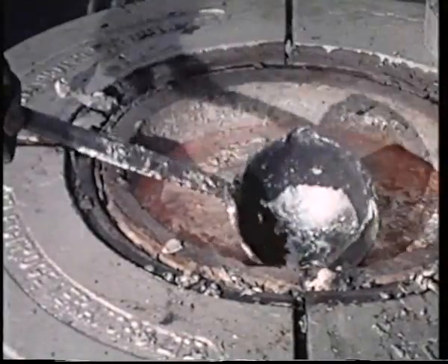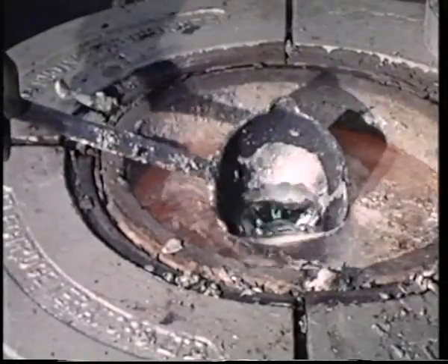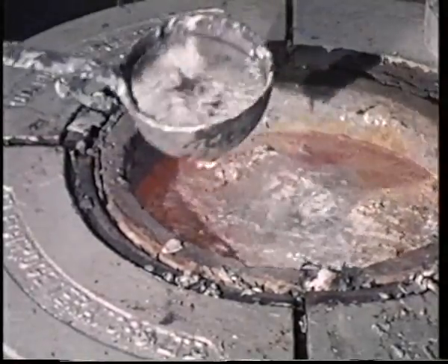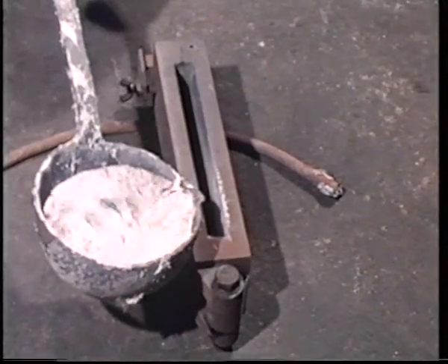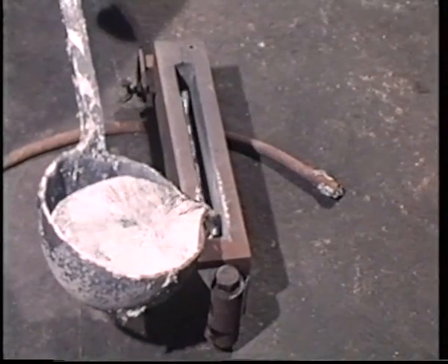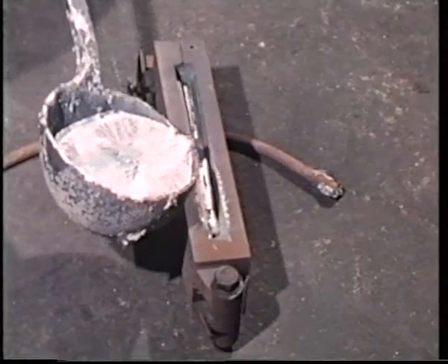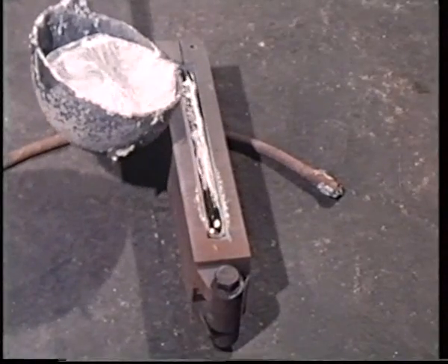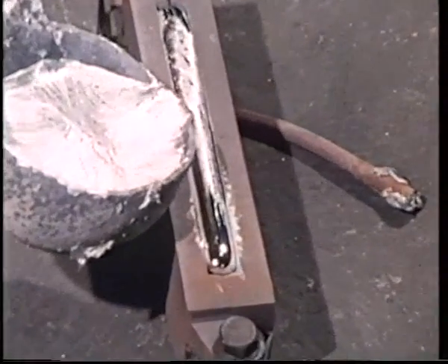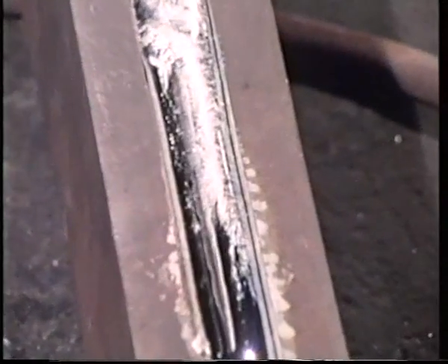This new material we formed is called an alloy. It's an alloy of aluminium. To find out how alloying has affected the strength of the aluminium, we must cast a suitable test piece. To compare forces, the alloy test piece must have exactly the same dimensions as the aluminium one we tested earlier.